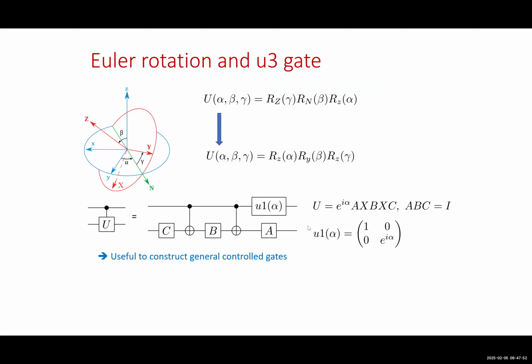You do the RZ, little z, with alpha, so align this to n, and then with respect to n, align with beta angle, rotation with respect to that, align the z axis, and then with one z axis, you just need to align xy. Okay, but these are in terms of axes that are not really fixed, like n. You don't really know what n is, but by the intersection you can find it, but you want to convert to a fixed axis, for example, x, y, z, right? And then you get these two.